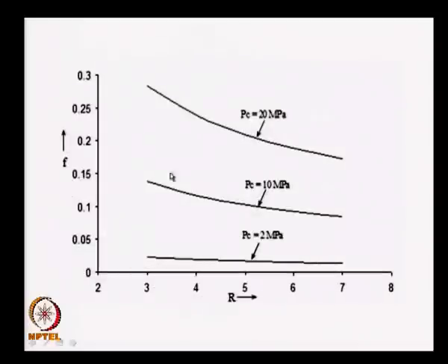Second is the same thing, if I now translate into chamber pressure, I find that the fraction of the propellant which flows through the gas generator and is not expanded adequately, at high chamber pressure I have a large fraction. Maybe for this particular example, I took the mixture ratio of the gas generator as something like 0.6. I took the overall mixture ratio of the engine as something like 4, and for eta P as 0.6, the temperature of gas generator as something like 900.